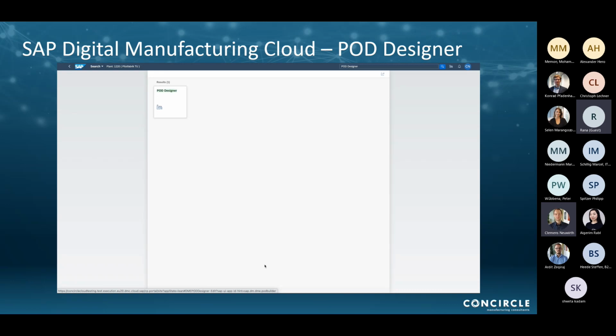You can see the layout. You can choose different containers here. And also there are the different plugins of the DMC, which are the standard plugins here. And on the right side, you see then the few buttons we already clicked on, and you can configure each of these buttons. For example, you can click on the Start button, can also see the configuration for it, so how big the button is, the colors of the button, and also the actions of these buttons.